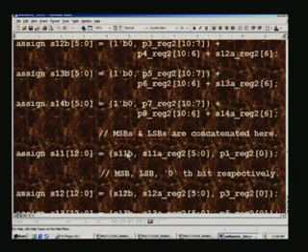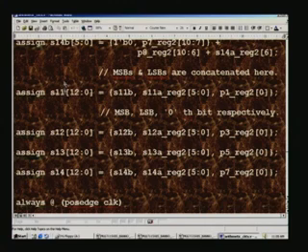Concatenating is putting together as a single number, that is this one, and we should also concatenate the last bit we have not processed, which happens to be the very same P1 LSB here, and that is how we get the result of the first stage here. For the first stage you have 4 such outputs. This is the first stage of addition that we have seen in the diagram earlier for the algorithm, and these are precisely the same thing here.